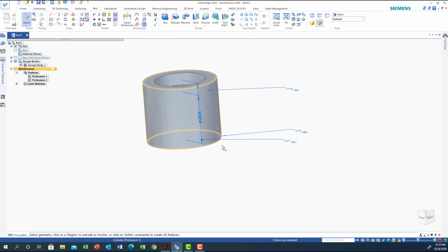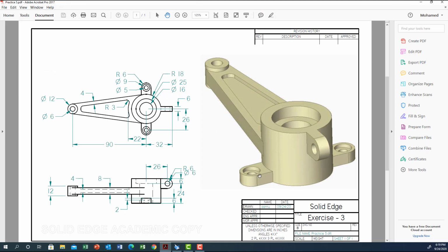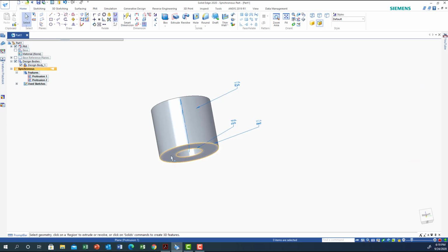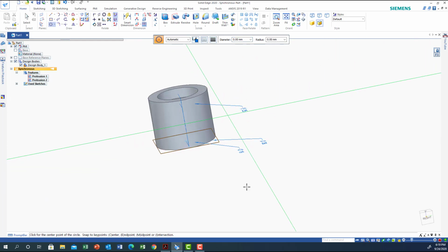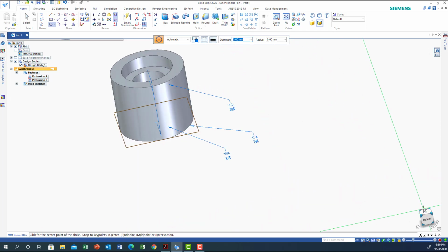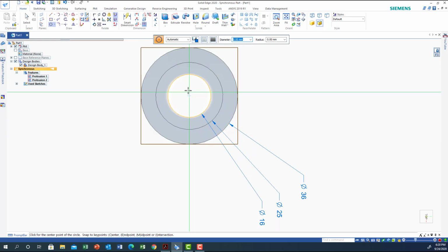Now we're going to go to the bottom of the surface here to start drawing these two wings. So I'm going to go to the bottom of the surface and highlight it. Let me start with the circle by center. I'm going to come to touch the plane, and when I see the F3, I'm going to click on the F3. This automatically will lock me on this plane, so any drawing is going to be in this plane. So I can move it around. I'm going to go to the top view. Still, anything is going to be on the same plane here.